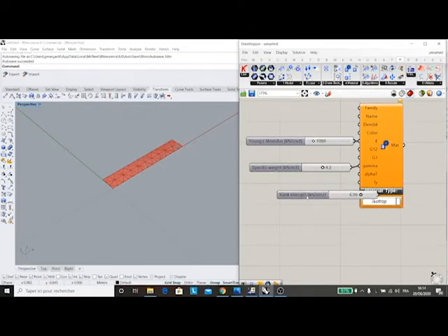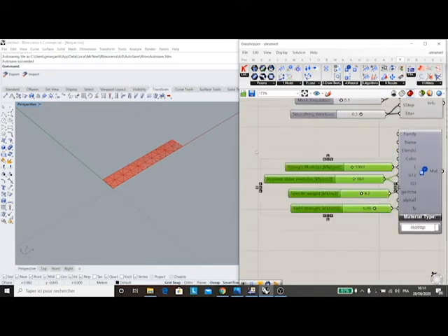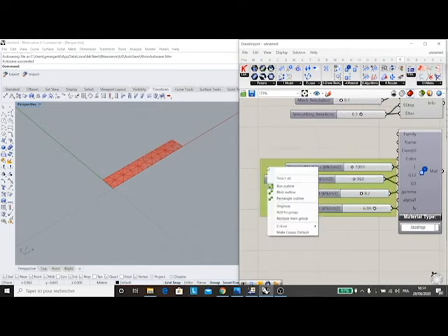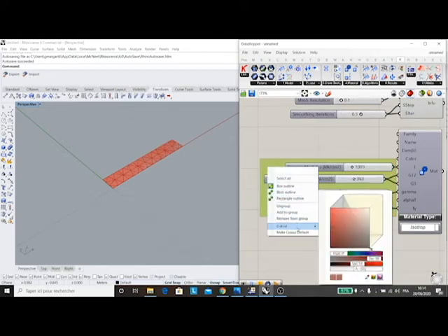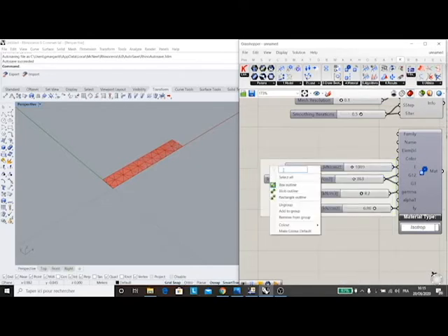I continue with the strength, and then the last value to make it work. So these are the values for poplar wood. You can use them to test your ideas, but you should pay attention that if you're making a paper model that you want to test in Karamba and you want to model it in Rhino, so you have it with different dimensions, in a different scale, then you have to put the right materials here, the paper properties.